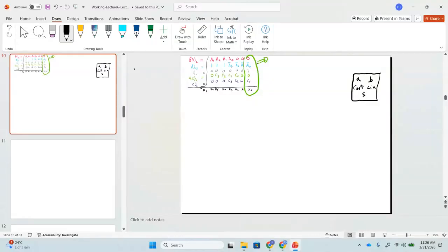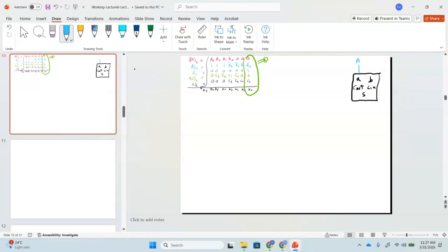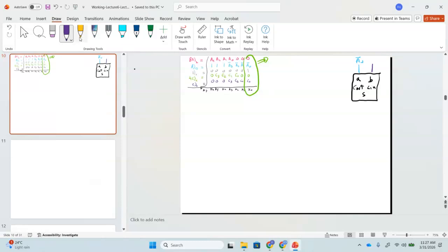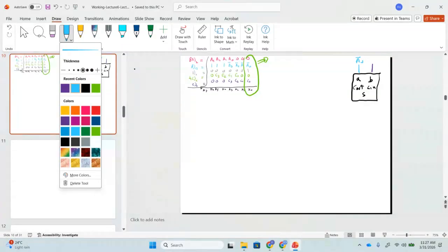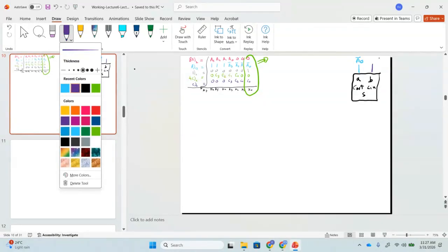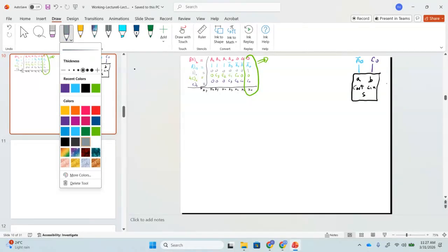Okay, now please look at here. In the least significant stage, we need to add A0 bar, 1 and C0. What will be the value of A here? The value of A will be A0 bar. Now what will be the value of B? The value of B, I can make it C0. Can you see the purple color? In the blue color, it is A0 bar. The purple color is C0. And then the one is here.